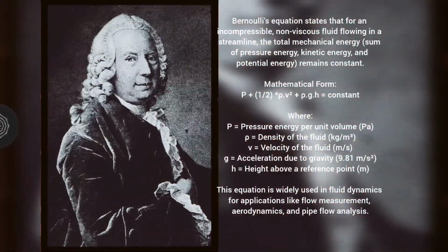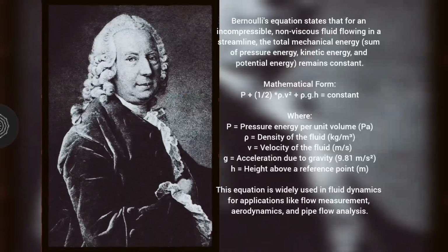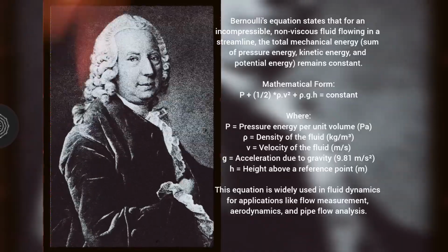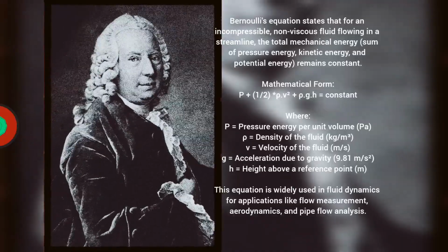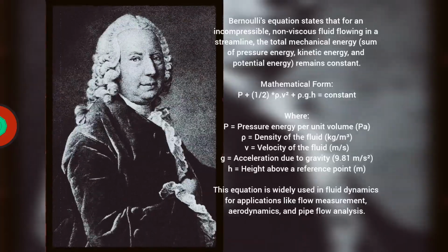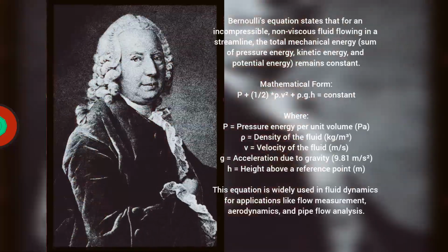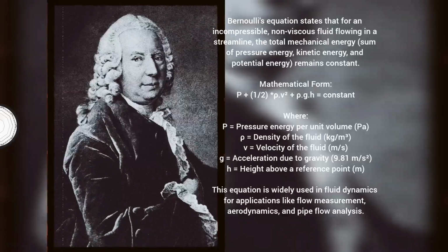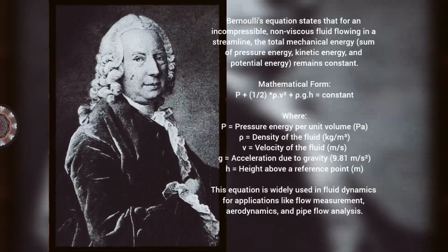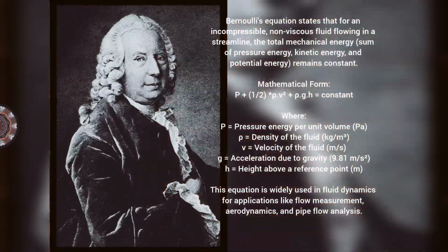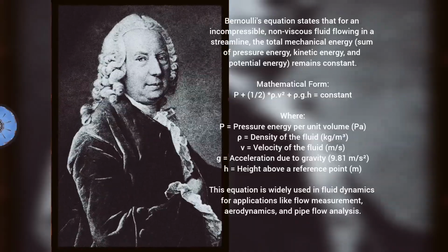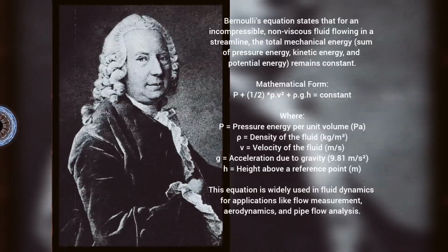That makes sense. So it sounds like Bernoulli's equation works great in a perfect world, but didn't they say there are some conditions too? Oh, definitely. The candidate correctly points out that for this equation to work, you have to assume a few things about the fluid. Like what? Well, first, it has to be incompressible, meaning the density stays the same no matter what. Okay, got it. What else? The flow has to be steady, no sudden changes. Smooth sailing. Exactly. And ideally, no viscosity, meaning no internal friction, like things moving along without any resistance. So no friction, no problem.